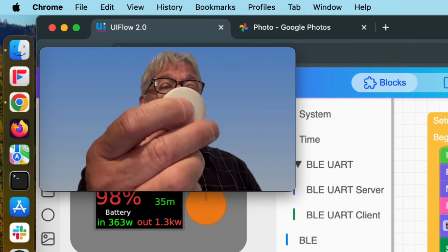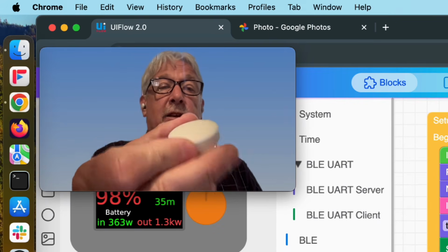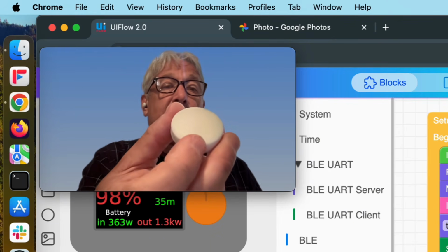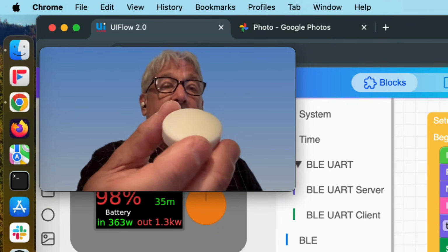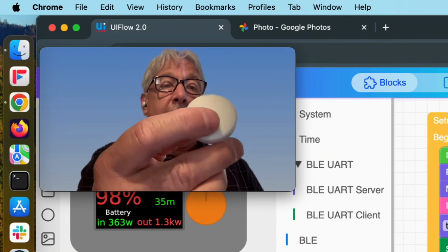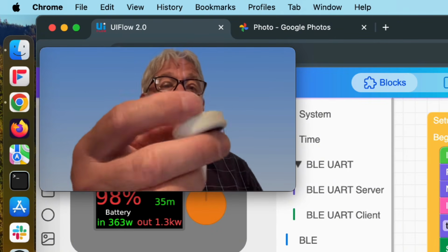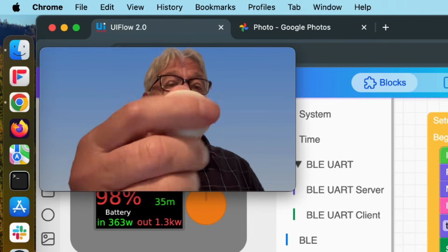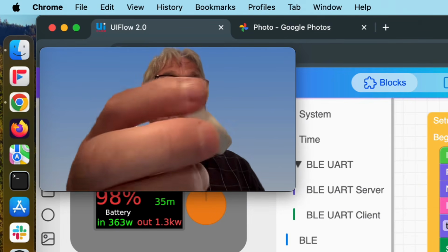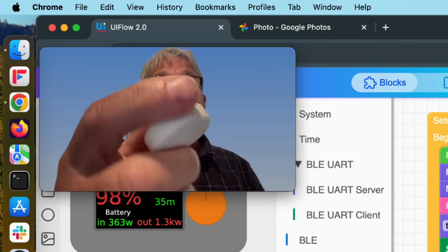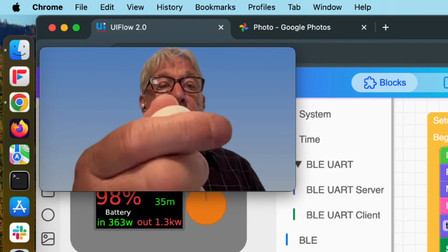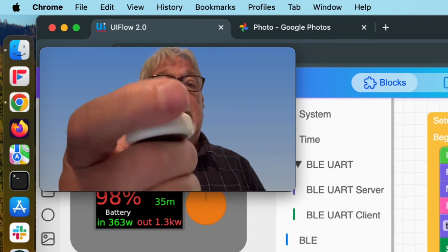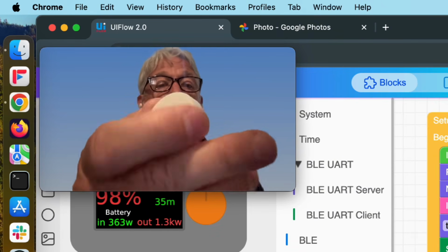I used this. The batteries have run out at the moment, but what I did with this is I made a universal remote. So I used the Bluetooth Low Energy HID, human interface device, and I programmed this. First, I had to calibrate the uncalibrated sensors. So you hold it down and it goes into calibration. You have to spin it around in all axes, and it flashes a red light, and it gets the highest values of all these sensors and the lowest values. So it records the minimum and maximum of the magnetometer sensors, for instance, in 3 axes.